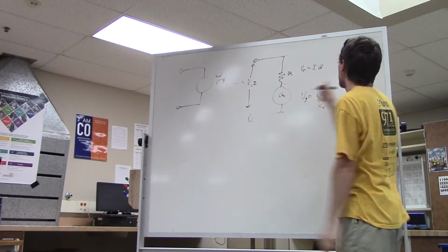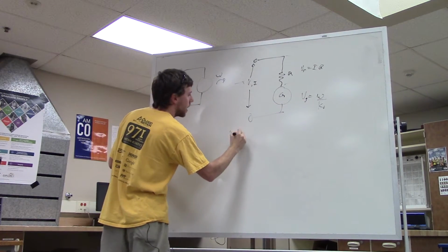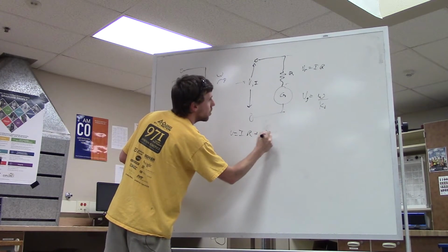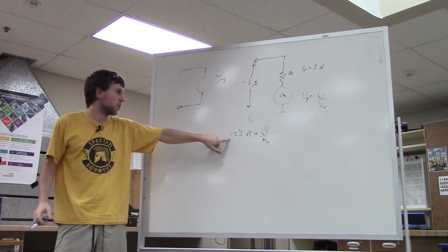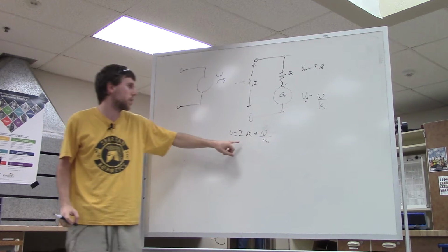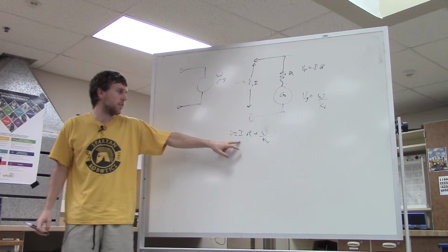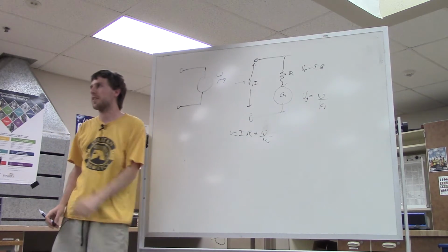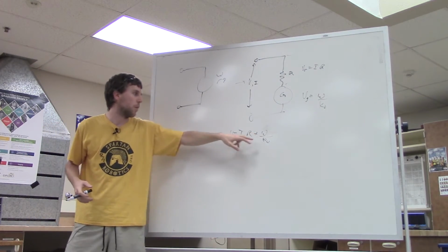So the voltage drop across your motor is then V equals IR plus omega over kV. So this says that if we know, say, the voltage across the motor and the angular velocity and our constants, we can figure out the current, for example. But this isn't enough to actually simulate the system because we don't know how the angular velocity evolves with time. When we apply a voltage, we don't have anything telling us what it will be.